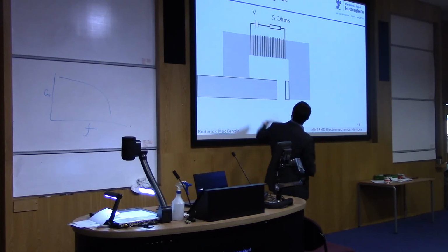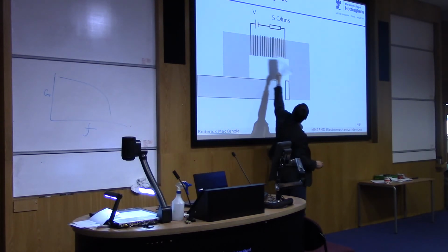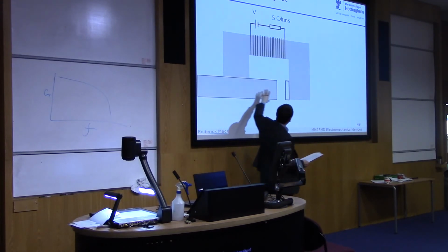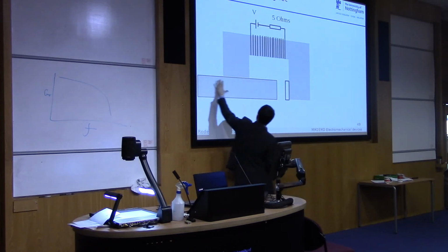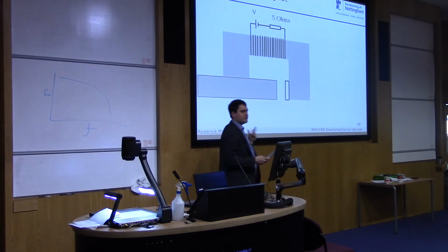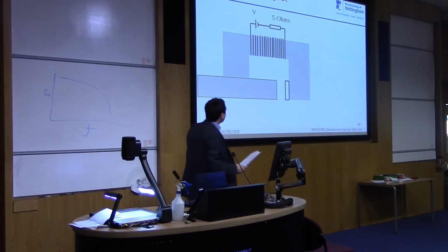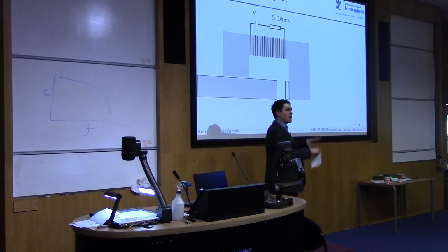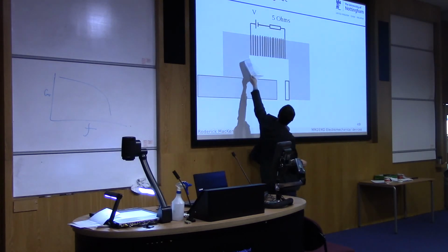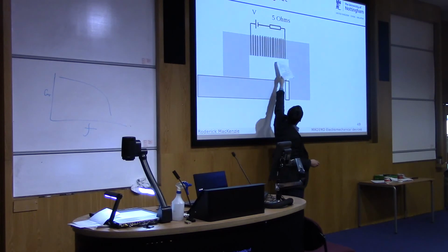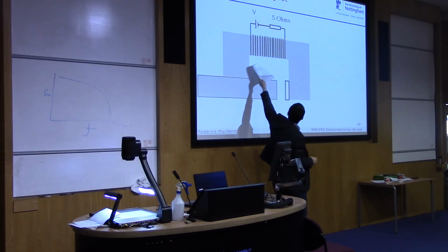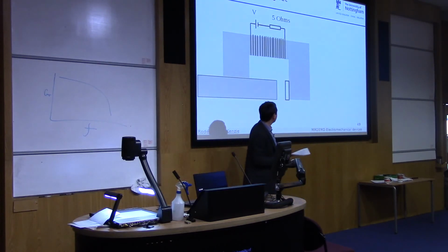He's got a magnetic circuit here, and he's made the problem a bit more difficult because this time he's got an air gap that can move. So he's got this bar that can slide in and out, and he's going to ask you various questions about it. I know it looks scary, but what we can pull out of this picture is, again, our source of magnetic flux, so our phi. That's like our V in our circuit, the driving flux.